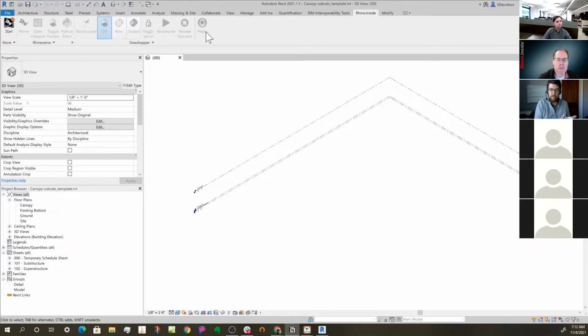Currently, it's important to understand that Rhino's not running quite yet, so it's not taking a license. And of course there's Revit. Once I hit this button and it loads the rest of this toolbar here, then it uses a Rhino license, because what it's done is it's actually taken Rhino and loaded it inside Revit's memory space. And so now it's still technically one application, it's Revit, but now Rhino is running inside the memory space of Revit.